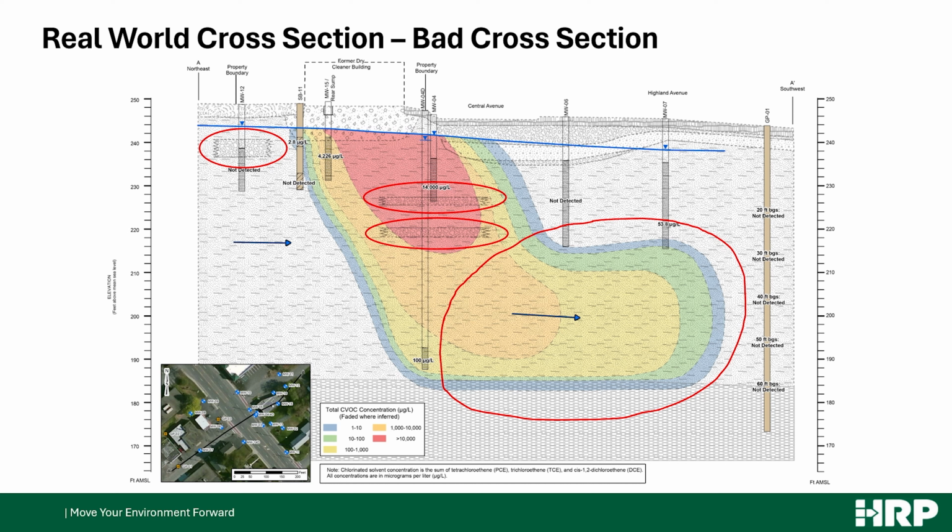And I think I'm going to make one more point that I know we're going to be bringing up quite a bit as we get into CSMs and even going forward. We started this with the soil boring log, and a lot of times, unfortunately, that is treated as a kind of entry level task. We get somebody out there with limited training, take the boring logs, write down what you see, and it's almost a throwaway, and it shouldn't be, because that is something that we're going to be basing remedial strategies on, that data. So that data has to be good.